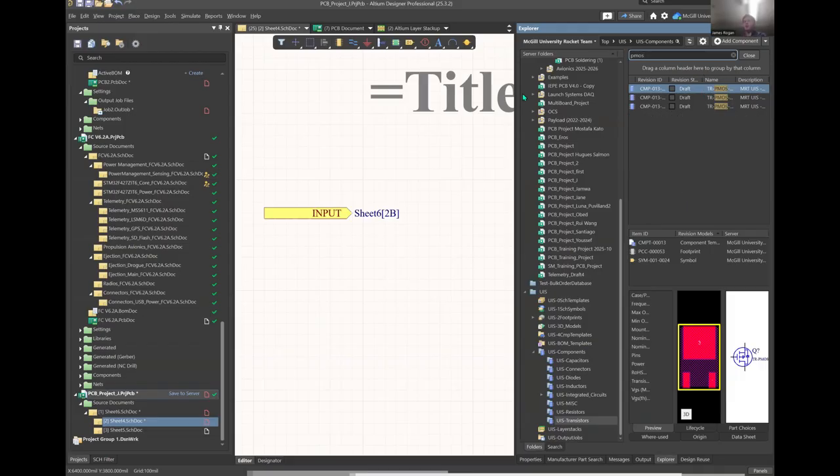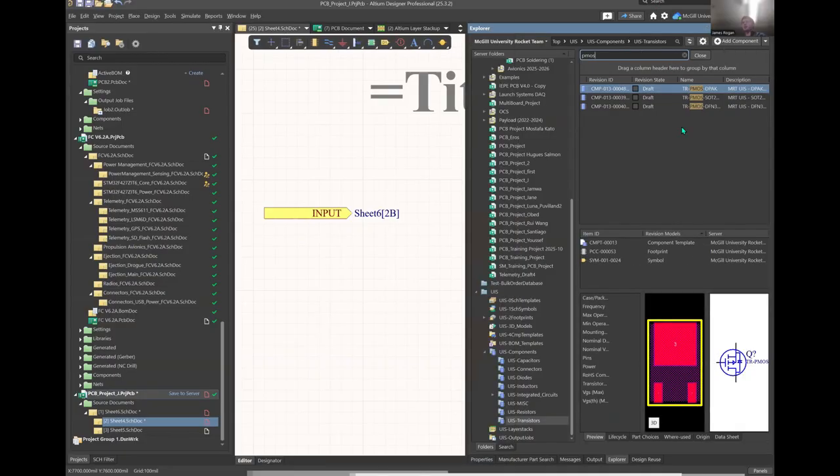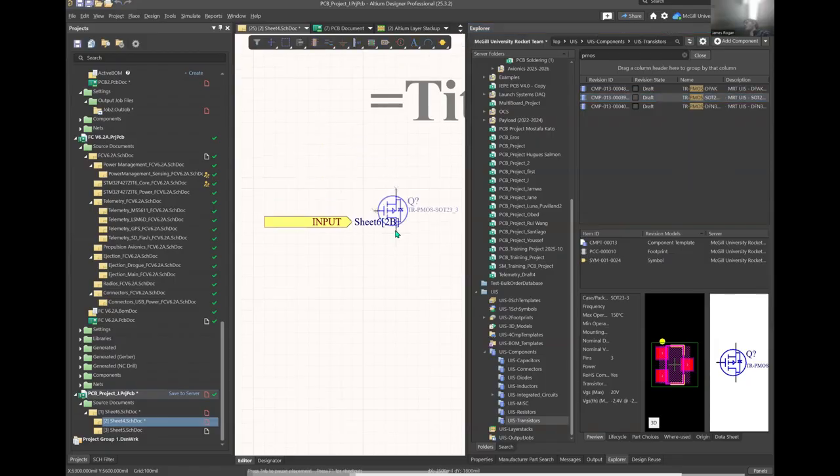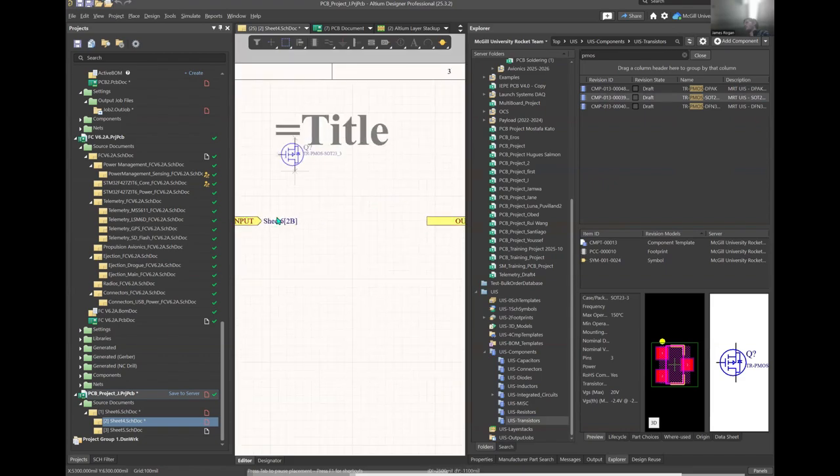It's okay for today if you don't know what some of these devices are, but I'm just showing, let's assume you've decided that you need this component as part of your circuit. You'll find it here, and you can right click on it, say place, and then it's going to open up this menu. You can drag it around, hit spacebar to rotate it, and hit X to mirror it on the Y-axis, and Y to mirror it on the X-axis. And then yeah.